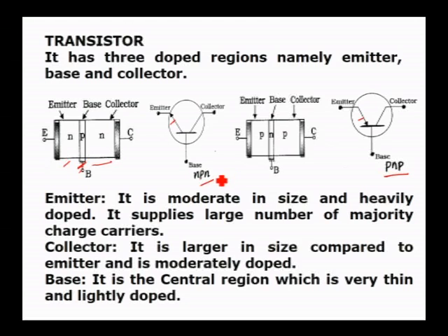In this case, you can remember NPN transistor like arrow not pointing in, the arrow is pointing out. Basically, the arrow represents the conventional flow direction when you are using the transistor in a proper manner. And when you bias, usually emitter base junction is forward biased and collector base junction is reverse biased.